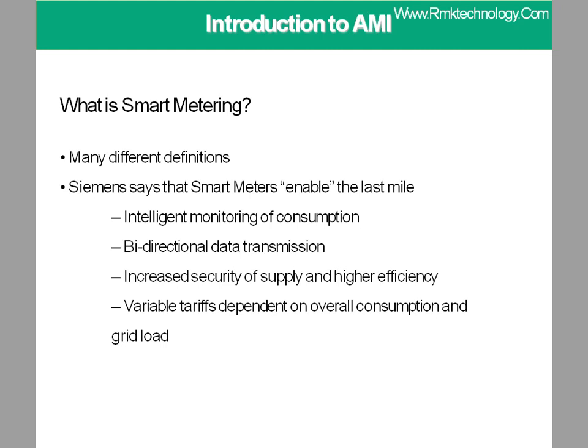So basically in a smart metering solution both the utility company and the customer should be able to see hourly, daily, weekly and monthly consumption. Also in this system meters can be directly reached from the system for control of meters for remote connect or disconnect. Also since in this system meter readings can be available every 15 minutes or half an hour, tariff can be applied based on time of day.